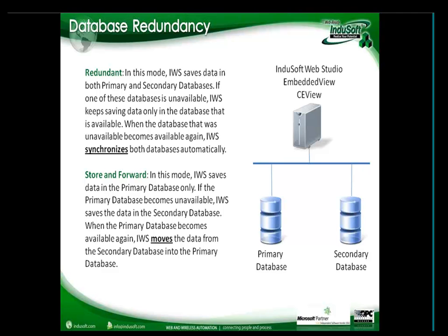There are two modes of database redundancy supported by InduSoft Web Studio. One is called redundant. The second one is called store and forward. In the redundant mode, InduSoft saves data in both databases, the primary and the secondary, simultaneously. So all the data is saved in both databases.